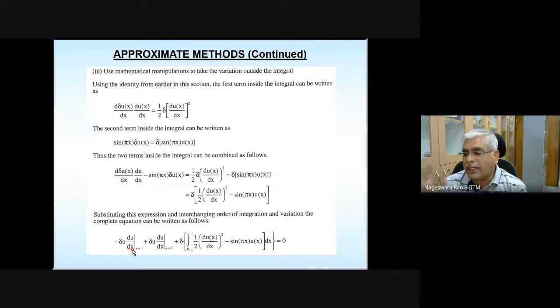If you did not like that explanation and you don't agree with that, then once you get the admissible trial solution, you can find what is variation of U at the point where essential boundary condition is specified, and then check whether that is equal to 0 or not. That way also you can do. Anyway, think about it. Maybe you think about this problem and also look at the assignment problems. Then you will get more questions. Maybe we'll discuss in tomorrow's class.